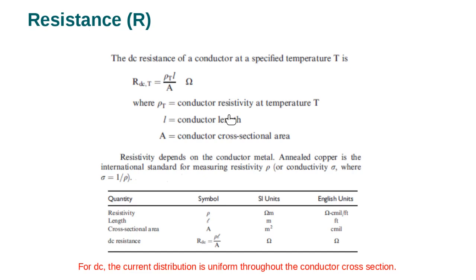The size of the wire is thicker than for connecting lights. For lights, the wire will be 1.5 millimeter or 2 millimeter, while for AC it will be 4 millimeter or 6 millimeter, and so on. So to carry high current, we increase the area, and this will also reduce the resistance.